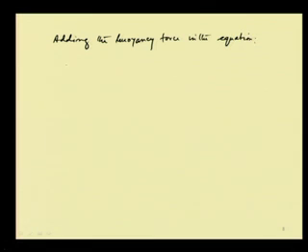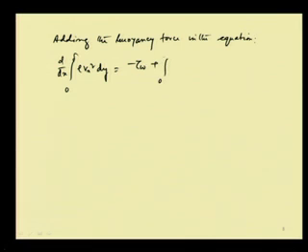What we get is d dx of integral 0 to delta rho Vx square dy equals minus tau w plus integral 0 to delta rho g beta (T minus T infinity) dy. Already we have seen that rho g beta (T minus T infinity) into dy gives the buoyancy force.